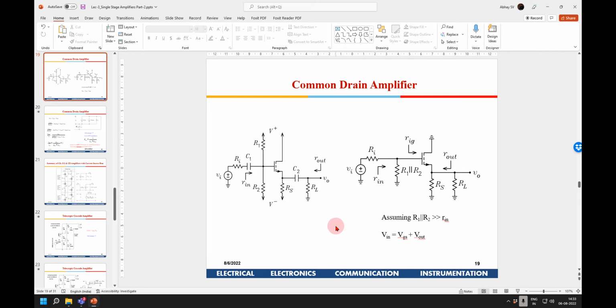Sir, I have one doubt. In the LTspice simulations that you have currently shown, we have removed both the capacitances, right? Correct. So how did the DC component of that first output stage, the CS output stage, get filtered out? No, it is not filtered. That is acting as a biasing voltage for the next stage. If that is matching, you can club it. That's what I said.